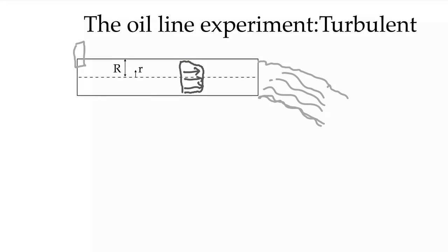Now we put the pin in, and the flow transitions to turbulence, and therefore we get a jet coming out of it that looks like this. We can see that it's a turbulent solution. It's more jagged on the edges. All of those features have changed. But now the resistance is higher. The pump is seeing a higher resistance because the pressure drop is higher, because the shear stress is greater on the walls, and therefore the flow rate starts to decrease.